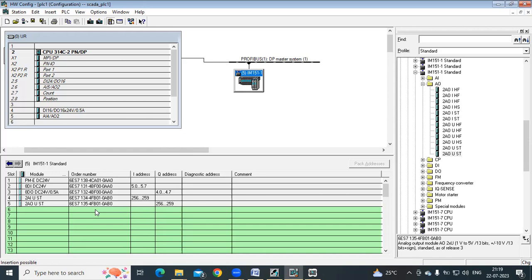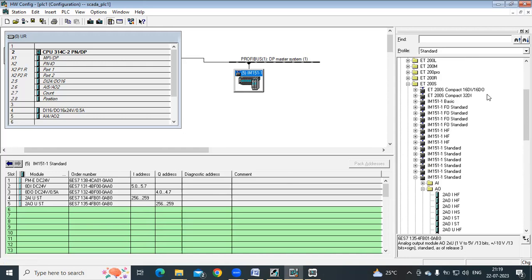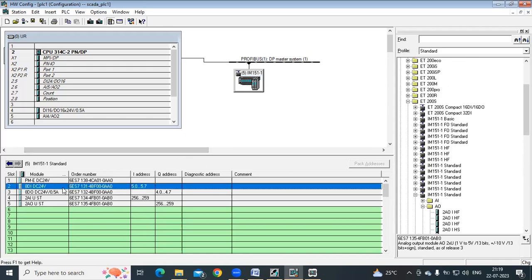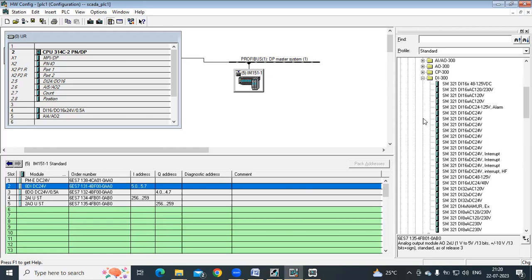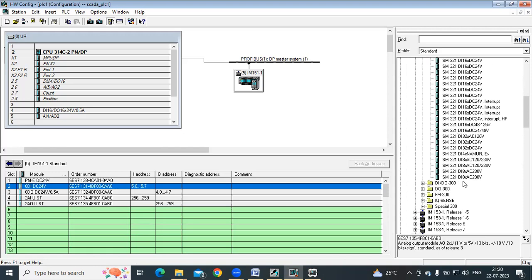Okay. So in this ET200S, the modules I'm configuring have a maximum of only 8 DIs available. Okay, in one module, you can have only 8 DIs. The older modules, like ET200M, will have up to, for example, you can see here, how many? 32 DI.